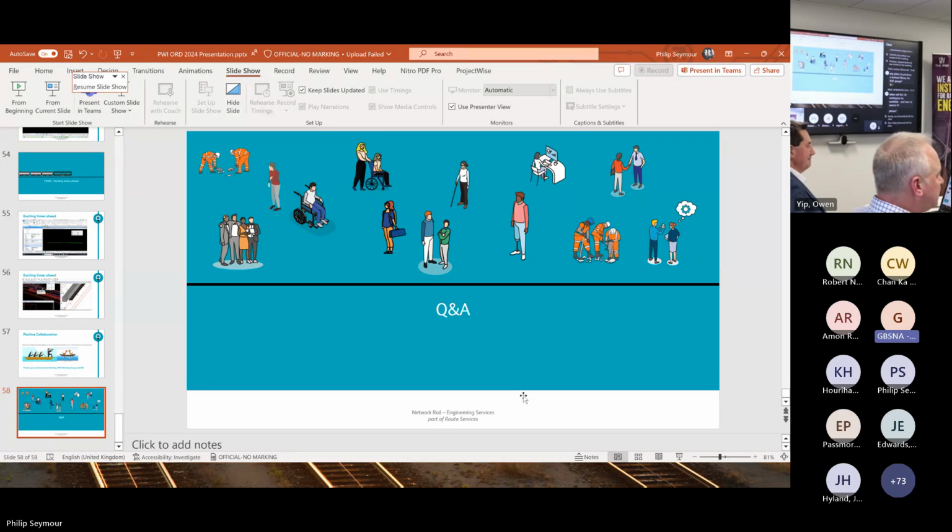Is there any questions in the room? Yeah, go. Is there any alternative to the ALG file? So an XML export or such? No. Everything's stored in the DGN. Again, it's all our rules, and the way we call this design intent stuff works across references. You can save, obviously, as an XML file. You can dump that out and report if you wanted to, as a backup and import in. There's nothing stopping you doing that.